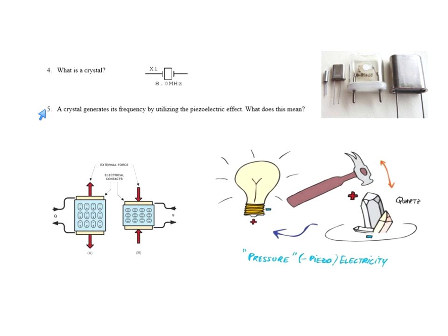But how does a crystal work? A crystal works by the piezoelectric effect. Here's how the piezoelectric effect works. If I mechanically twist this crystal, it will generate a voltage. When I release the twisting of the crystal, it'll pull voltage in or power in. So, well, that's a little bit confusing. Look at the diagram down here. If I pull it apart, it generates one polarity of charge. If I push it together, it generates another. We typically call this twisting, and this is greatly exaggerated here.